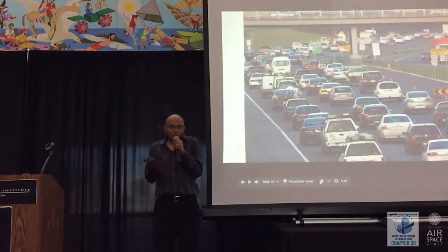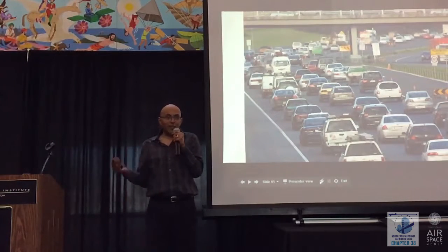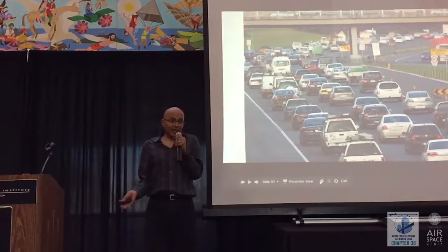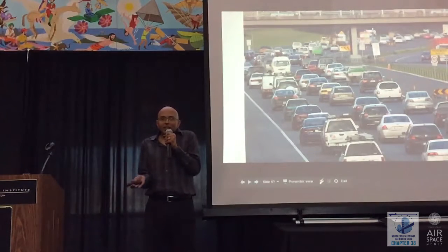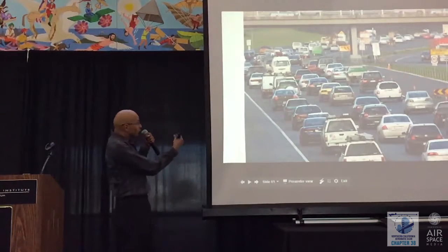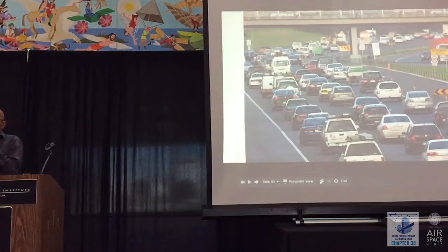Because once again, as Wolfgang Langewiesche told us, you have one job as the pilot of an airplane. It's to control the relative wind. We don't fly airplanes that have rocket engines. So the only way we can get the airplane to go where we want is to control the relative wind. And every loss of control of the type that we're talking about here was preceded causally by a loss of control of the relative wind. There simply is nothing more important in flying an aircraft.